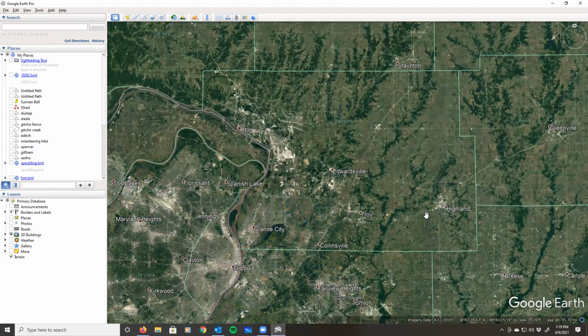The scale factor is the actual linear distortion between the ellipsoid distances. That's what the projection is doing: it's transferring what's on the ground to the ellipsoid.